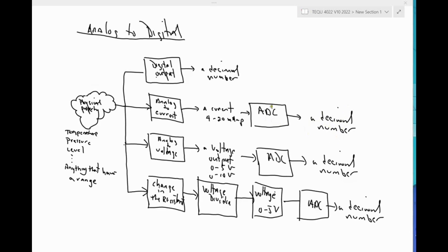This conversion of the ADC is done within the range of the ADC, and that depends on the number of bits of the ADC. Like in several classes before, I talked about how some of these ADCs come, for example, with 10 bits, others with 12, 16, and so forth. So depending on what ADC you are using is the conversion range. For example, for Arduino Uno, it's about 0 to 1023. That's typical for Arduino.